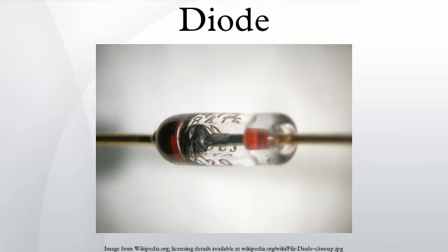A Zener diode contains a heavily doped P-N junction allowing electrons to tunnel from the valence band of the P-type material to the conduction band of the N-type material, such that the reverse voltage is clamped to a known value, and avalanche does not occur. Both devices, however, do have a limit to the maximum current and power in the clamped reverse voltage region.